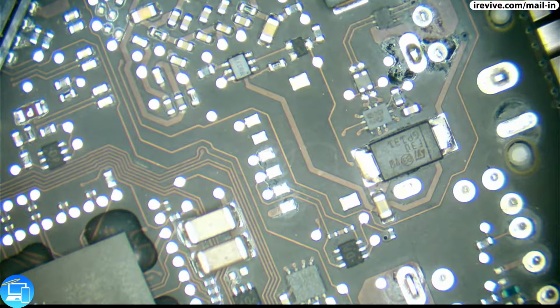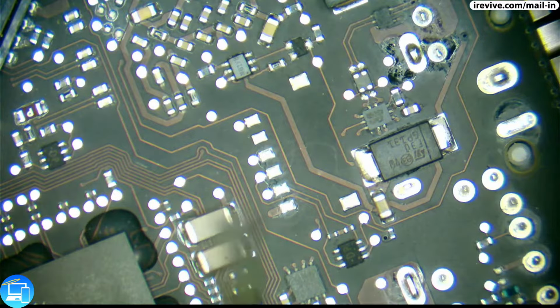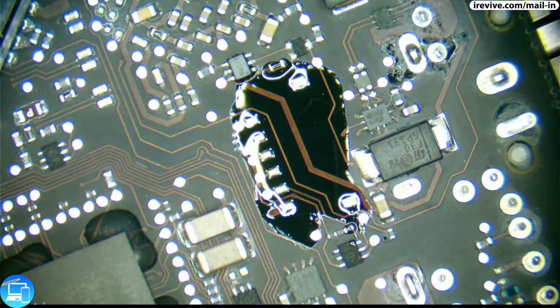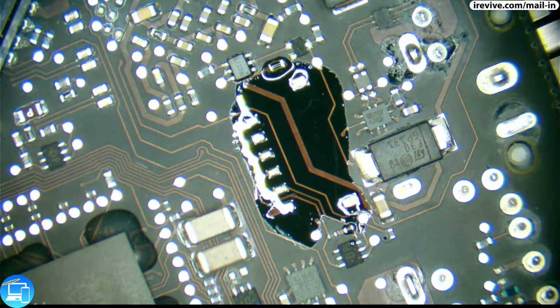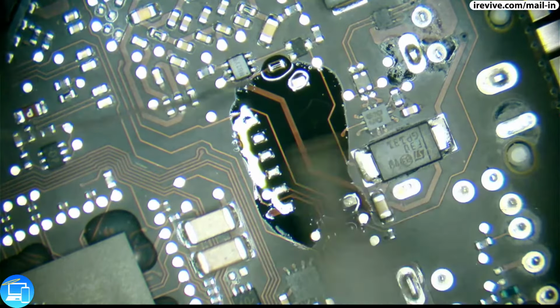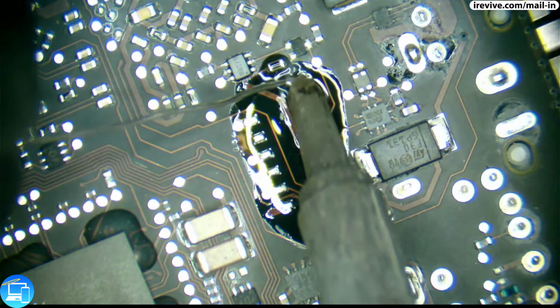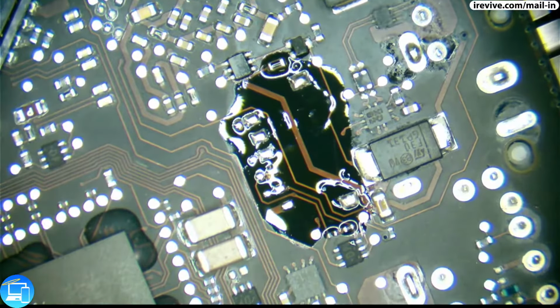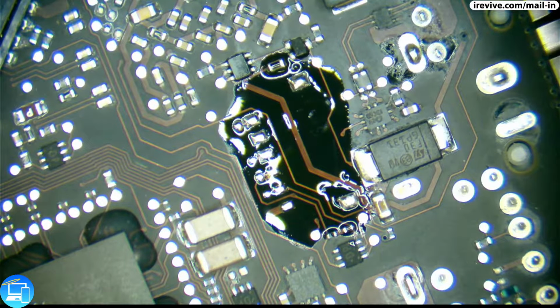All right, let's go ahead and turn on our soldering station, our fume extractor. Go ahead and put some flux down. Now, I'm going to just very briefly tin up these pads with some leaded solder. And now, we're going to grab one of these female Molex terminals.